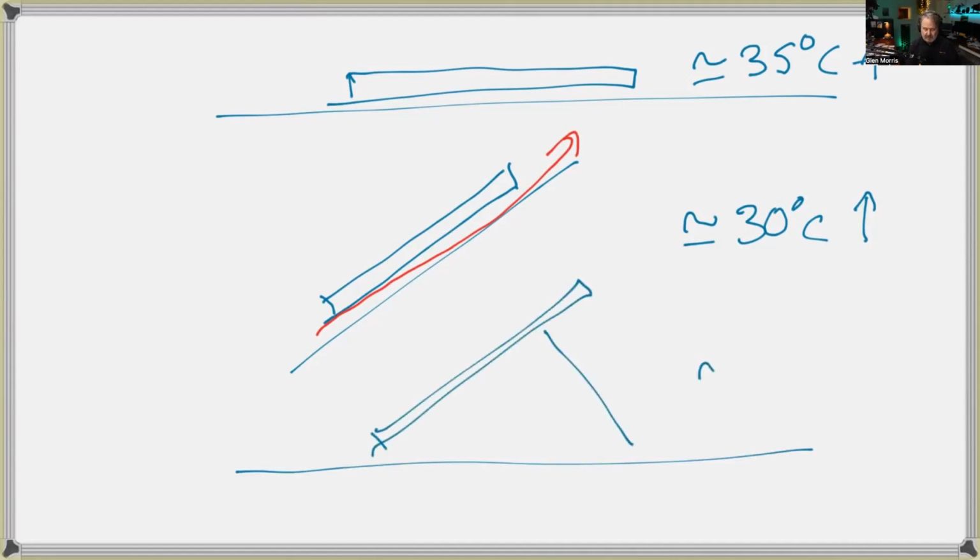Now we're about 25 degrees above ambient. And the reason for that is twofold. You're getting convection because of the tilt, but you're also, with wind, getting a little bit of breeze, exposure to any air movement. So they're more prone to cool. And therefore they'll run, in this case, about 3% more power than the flat roofs.